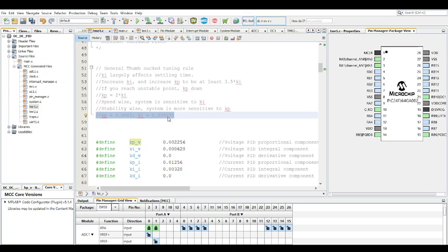And then what you can do is start to increase this a bit. Obviously, then you have to increase KP proportionally as well, and be careful. Watch your system. Make sure it's not getting unstable, because remember, if you go too high with the KP, then it will have issues. So once you hit that point, you just stop the KP. You pause the KP where it's at, and then you increase the KI independently of the KP until it's here. And then once it's here, please stop. Well, you can continue. It's your system to burn. But normally, I think you should just stop right there.